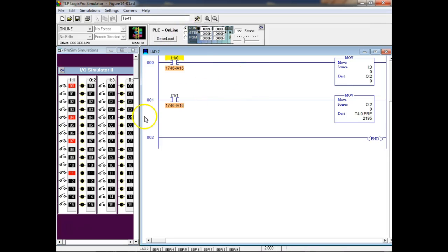So whatever I come up here and flip this switch, that should go to 1, right? This should be 2. This should be 4. This should be 8. This should be 16. This should be what, 17, right? Understand? So what I'm doing is I'm reading this input port. Now it's not displaying it in binary, it's displaying it as its decimal equivalent. So if you took this whole thing, all the ones I have closed, and wrote 1 down, and all the ones I have open, you wrote down zeros and converted it over, it would give you what?